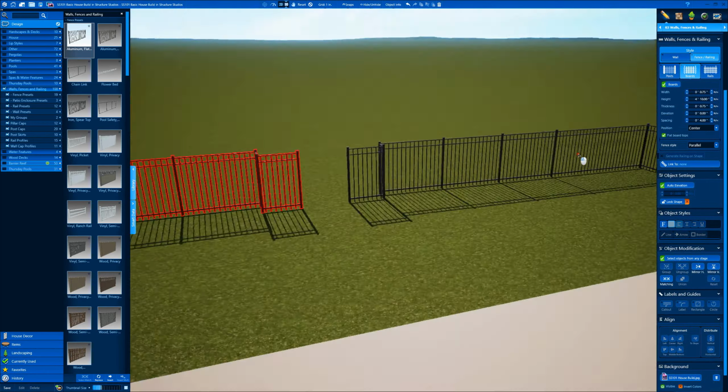So I'm going to go straight across. I'm going to snap to my opposite line, and I'm going to adjust that a little bit. Then, using my D outline tool, D shortcut key, I'm going to outline and follow this, all the way around, and click. And that is my second floor portion.